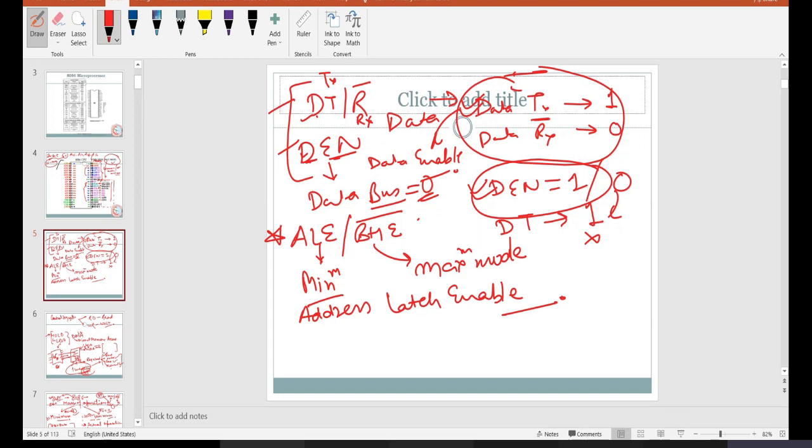So what is happening in those units? The data is traveling from one place to another place, and once it is traveling inside ALU, it will be processed. But again, it will be traveling from one place to another place. So what is the utmost important thing in a microprocessor or in a processing system? The address should be there. So address of what? Always remember two things in this processor study: source and destination. They must always be clear that from where this data or information is coming, and after processing where this will be going, where we have to store this.